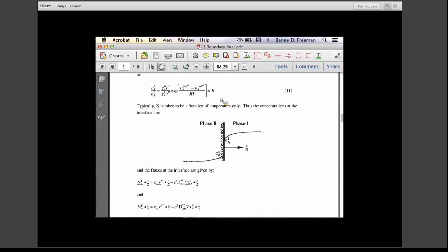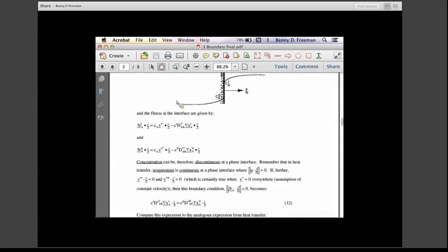And we can come back to the fluxes at the interface, and I can write the total mass flux as a piece that depends upon the average velocity, and also a piece that depends upon J sub A. Remember that the total molar flux we broke up previously into a piece that depended on the molar average velocity and a piece that we call capital J sub A. Well, for a binary system, capital J sub A is just Fick's law, right?